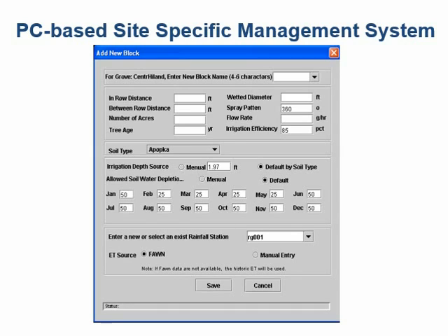It defaults to 85, which is a protection for you. If anything, it's going to overestimate your irrigation by just a little bit. Efficiencies for microsprinklers are about 90 to 95. So by putting the efficiency at 85, you're not going to run the risk of shorting yourself on irrigation. But you're not going to greatly over-irrigate either.